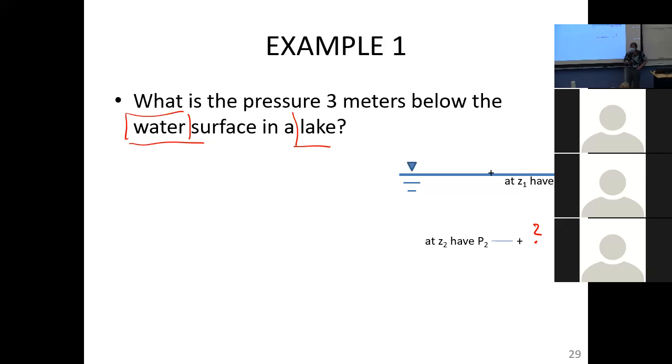When you leave here, it is incumbent upon you to know the temperature range of the systems you're looking at. So if you're talking about flow in pipes, water flow in pipes underground, that's probably going to be at the average annual ambient air temperature, wherever you are. Okay, so in this course, either the temperature is going to be given, and if it's not, room temperature. So again, that allows you to know the specific weight.